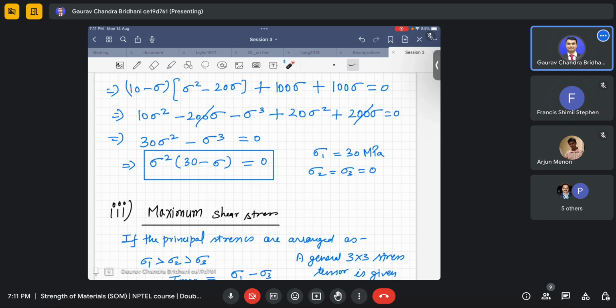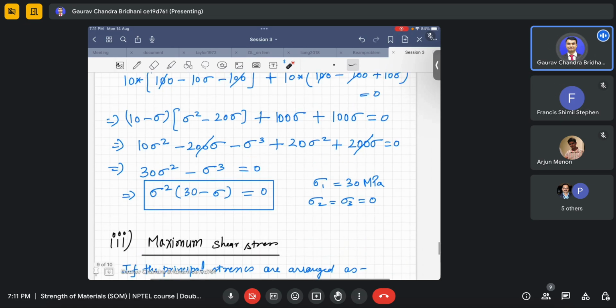And even you have seen in the lecture, if you plot the Mohr circle, from there you can understand why it is the difference between the maximum and the minimum. I hope you all have gone through the lecture videos. That is my request to you, because you will have a much better understanding. If you remember in the lecture, when the professor drew the Mohr circle with 3 principal stresses, there were 3 circles he drew. There were 2 small circles inside a bigger circle. So the tau max will always be calculated from that bigger circle, not from the small circles.